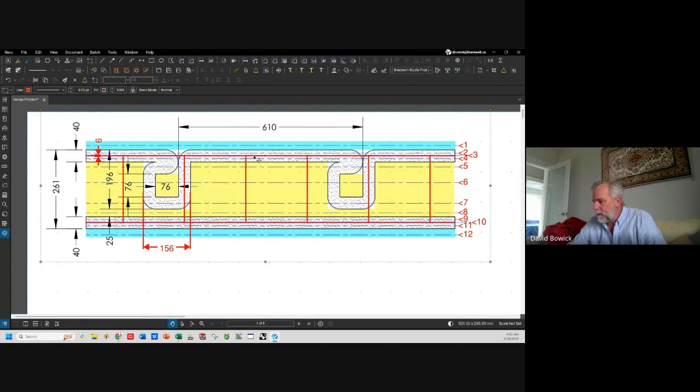So what you're seeing in red is my block lock arrangement. We're putting block lock reinforcement in to reinforce the wall. Our printed layer consists of the first layer, which is just concrete. There's a little skinny layer right through the wire, which performs differently because the wire is more conductive. There's a layer inside the wire, or inside relative to the wall, which is concrete that has the perpendicular wires going through it.